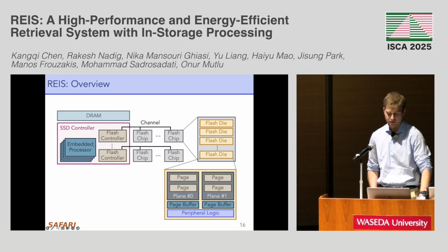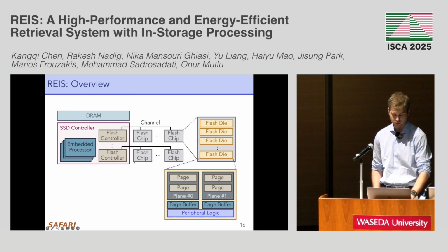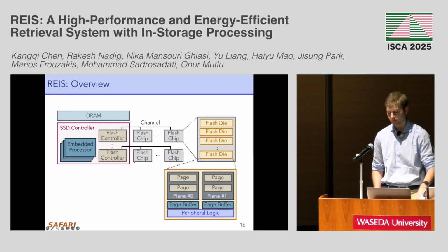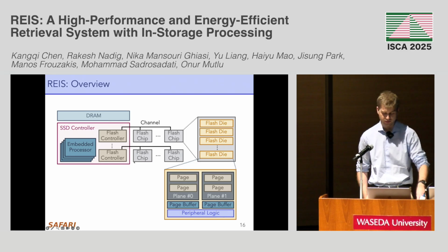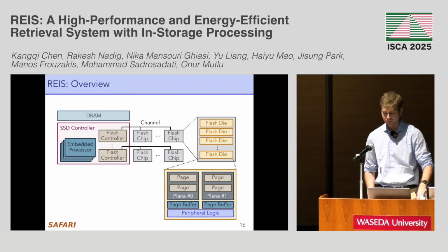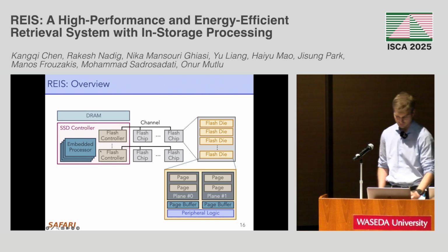We base REIS's design on the existing design of the SSD, which is comprised of multiple processors, a small amount of DRAM, multiple flash channels with multiple flash chips each, that are then composed of multiple flash dies. Each flash die contains multiple planes and pages, a page buffer for each plane, and peripheral circuitry, which all contain logic that can be used for computation.